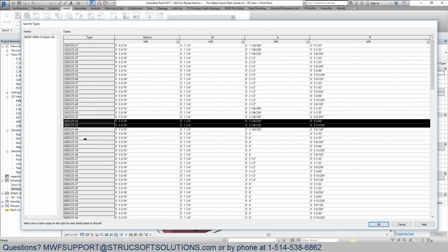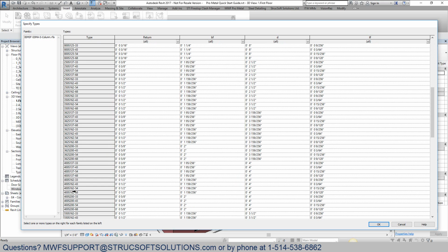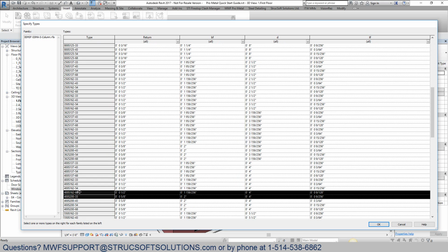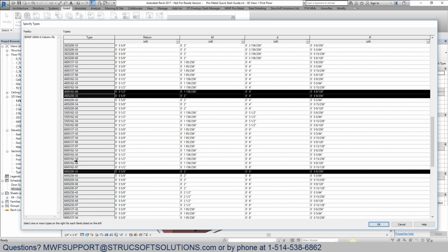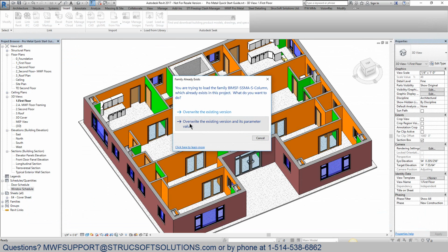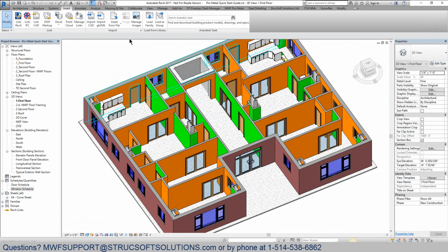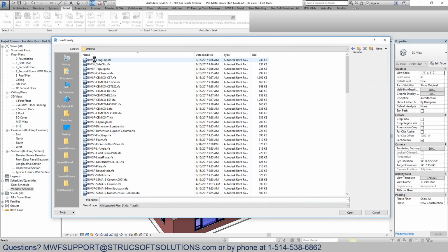There we go. I mentioned I have a 3 and 5/8 inch wall, so we'll take those two members right there. Same size, different gauges. We have a 4-inch member, so let's scroll down a little bit here. We'll grab a 4-inch, 400S 200, 400S 162, and a new 6-inch member. So we'll take in 600S 200 and a 600S 162 43. Perfect. Some of these guys were already in my project. Let's just override them and head back into our installation folder.